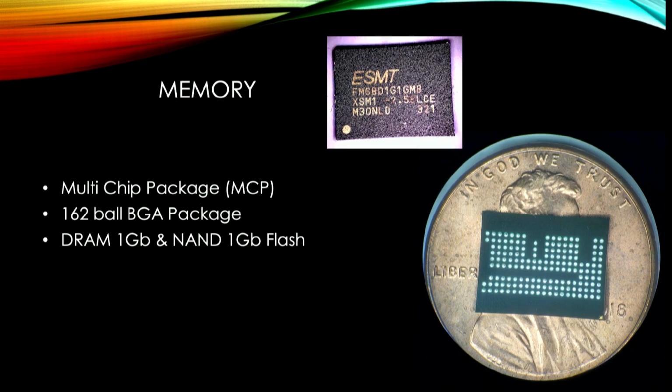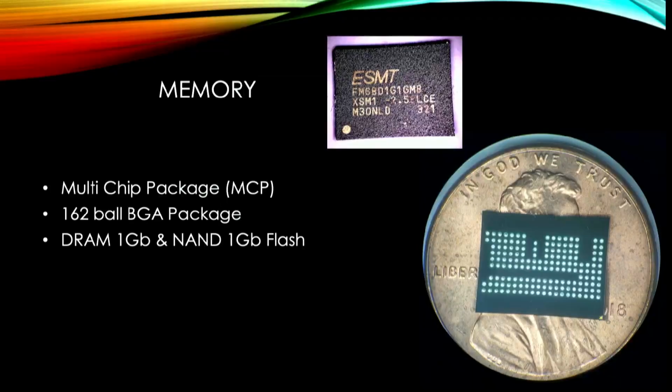If you find an eMCP, there are readers you can buy for like $100. You just drop the chip in and plug it into your box via USB. It'll mount the entire file system for you automatically because it has a built-in controller. You're not lucky with that here. Also, if you want to take it any further, chip sockets for these are horribly expensive. When they first started using them on a larger scale a couple years ago, a chip socket for a flash memory reader was upward of $2,000, and that socket was based on the dimensional size of the chip.